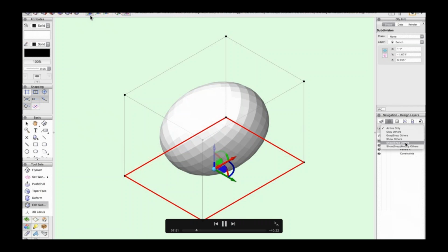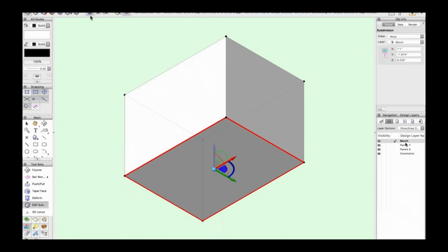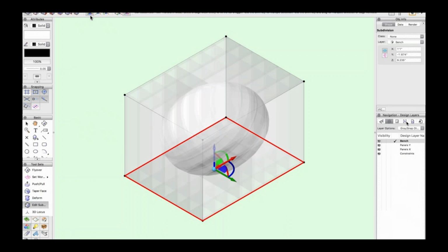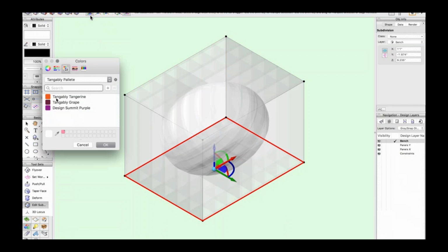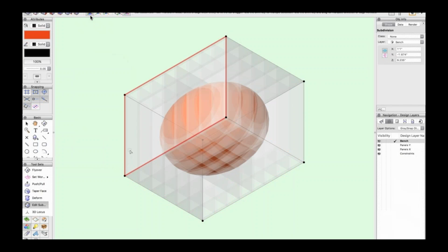And what that is essentially is an axis of X, Y, and Z. It gives you a point. You can click on that little blue point and move the whole face basically in any direction, X, Y, or Z. Well, the arrows on that 3D dragger are specific to the exact X, Y, or Z axes. So if you click on those arrows and drag them, then they'll move only in accordance to those axes.